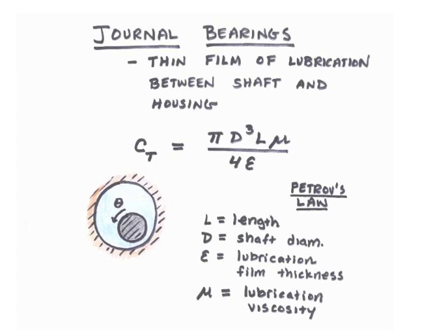All rotating machinery have some bearings to constrain the shaft and hold it in place while it rotates. There are various technologies that are available, including air bearings, ball bearings, and magnetic bearings. Each of these has some rotational damping associated with rotational motion. It is this rotational damping that is responsible for the shaft slowing when no motor torque is applied to the shaft.